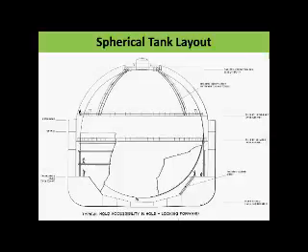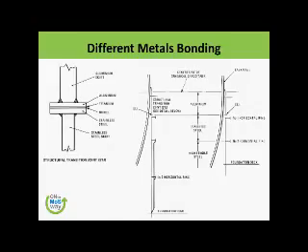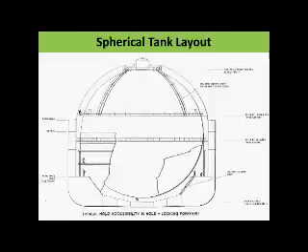Mind that you can see here the people can walk right underneath the tank, very close to the drip tray, to do the inspection. Most of the time, in most companies, the hold is filled with dry air. But if you have no intention of going into this hold space, then of course it is your choice. You can even inert it with nitrogen, etc.